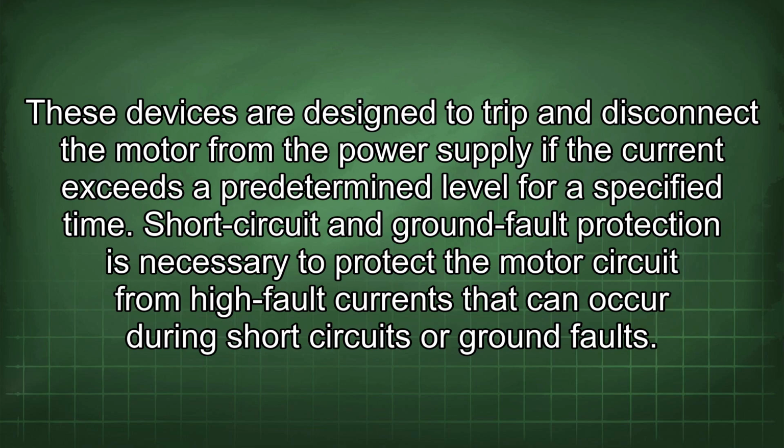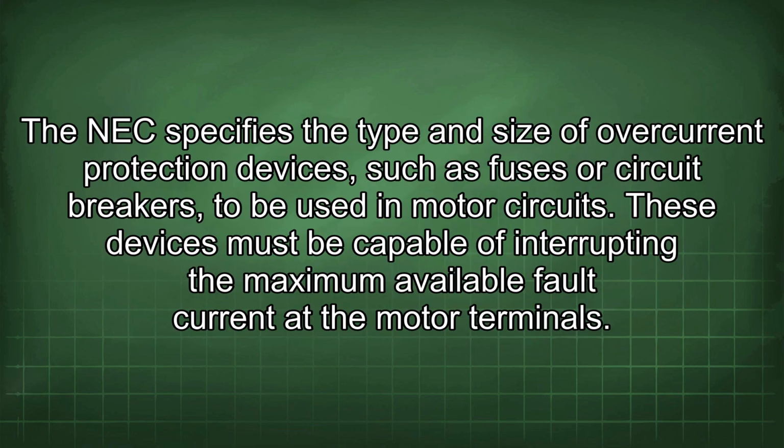Short circuit and ground fault protection is necessary to protect the motor circuit from high fault currents that can occur during short circuits or ground faults. The NEC specifies the type and size of overcurrent protection devices, such as fuses or circuit breakers, to be used in motor circuits. These devices must be capable of interrupting the maximum available fault current at the motor terminals.